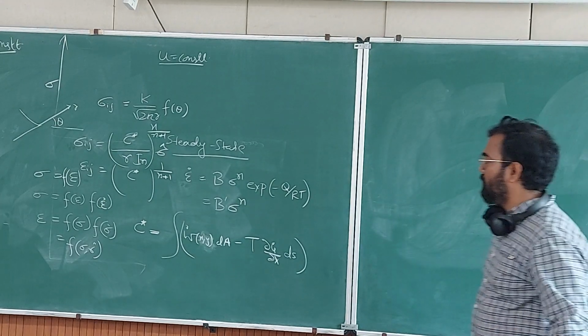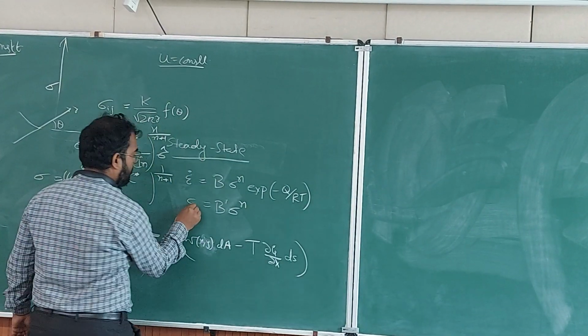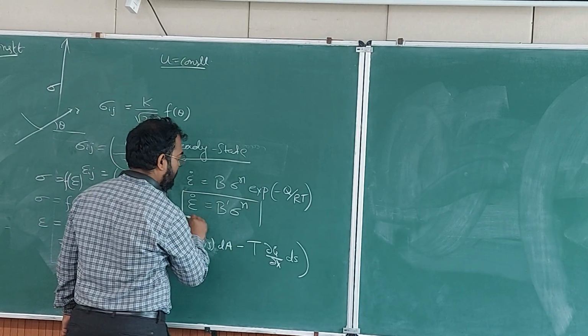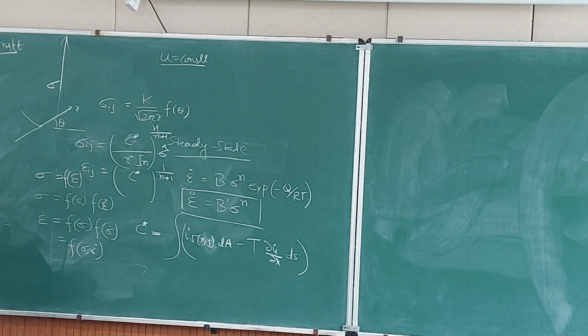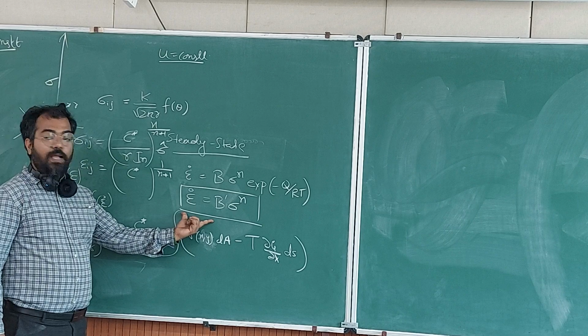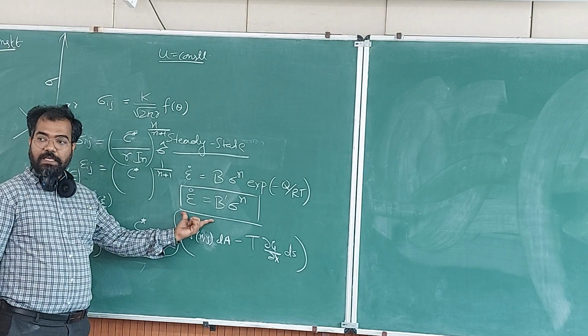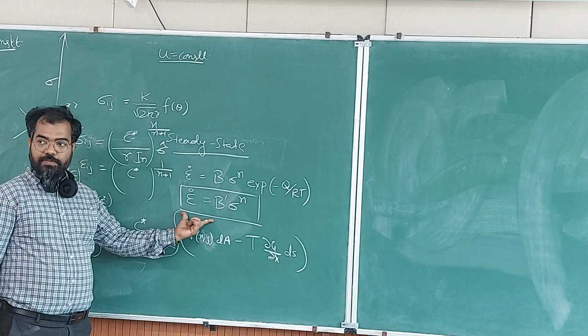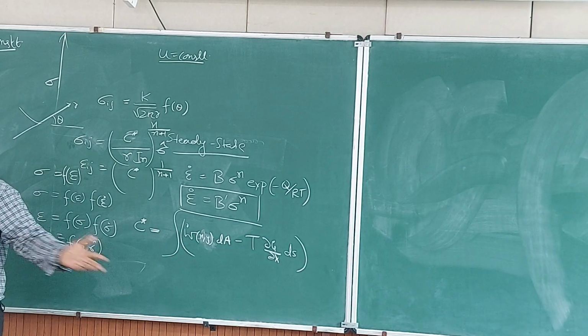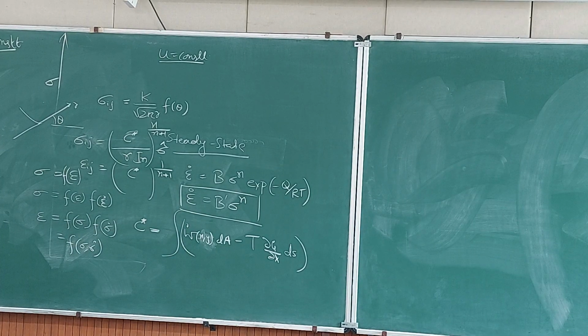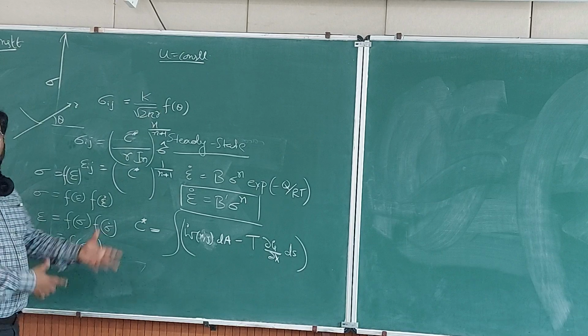And this is valid only in this situation. It is path independent. Okay, so this is similar to the Ramberg-Osgood equation in the elastic plastic case, where we define the J integral. So there is an analogy between strain and strain rate. You have an equation of strain versus stress, and you have an equation of strain rate versus stress, and with that analogy you define a new integral. So this was proposed by Hoff. Okay, and these equations were discovered by a lot of people.